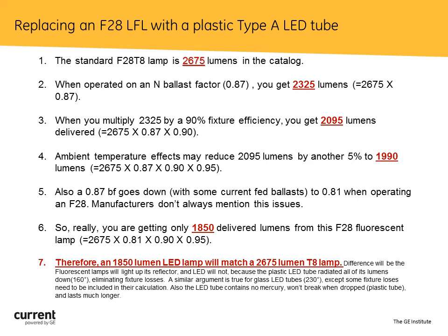Look at this slide, study it, and see how you can use it to determine what you would actually put in as a direct replacement for an old fluorescent tube. This is all a type A situation, and that fluorescent tube would be taken out and the LED would be put directly on it, assuming compatibility.